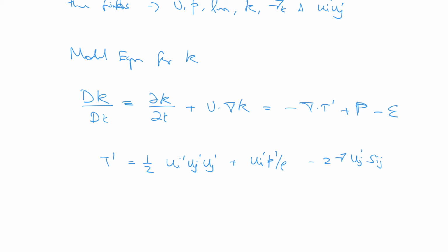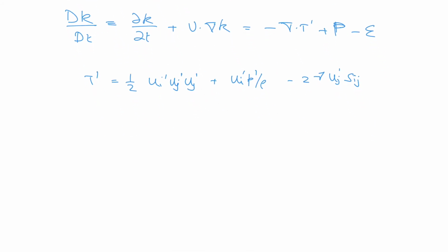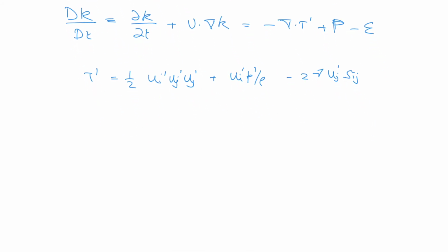Now what you can infer from this is the total derivative, temporal derivative, advective derivative, this is the transport, this is the production, this is the dissipation. In this equation, we have this dk by dt and this production term capital P, which are available in closed form. This epsilon, that is the dissipation, and this del dot t dash, these are all unknowns.